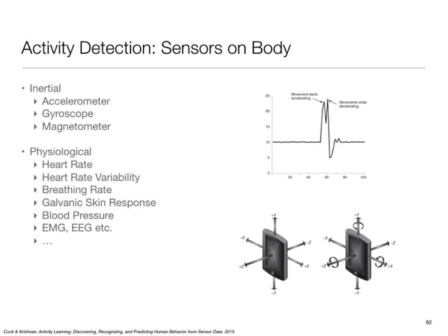So accelerometer, gyroscope, magnetometers, these are collectively called IMUs. Sometimes you will see things like 9 DOF inertial sensor. 9 degrees of freedom refers to the fact that the accelerometer has 3, it's 3D, the gyro has 3, and the magnetometer has 3.